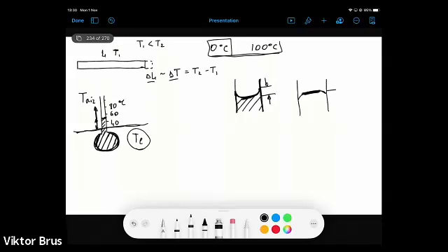Oh, yeah, you are right. We can locate it deeper. However, that is not common practice because you have some device, you fix the position of the thermometer, it stays fixed, and you don't usually change the position of the thermometer, since that could also change the properties of your device. So in order to have reproducible conditions, you keep everything the same in order to reproduce the conditions of the experiment. So you don't want to move any parts. The first thing. Second thing, it's not just like this construction of a thermometer.